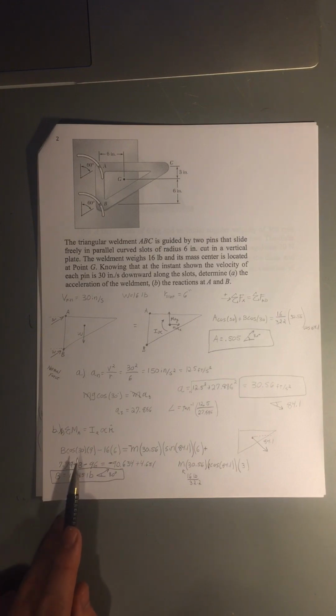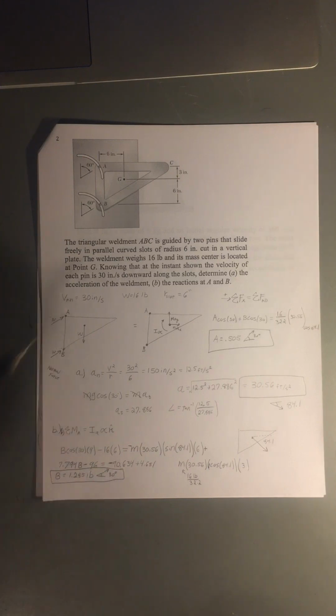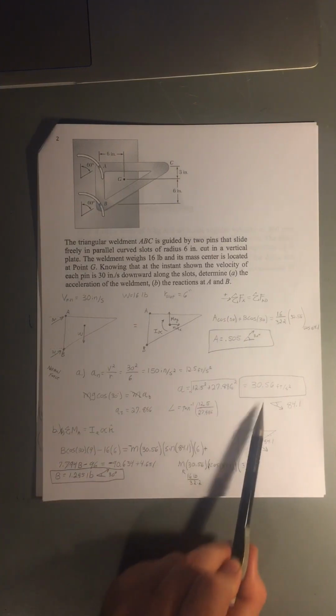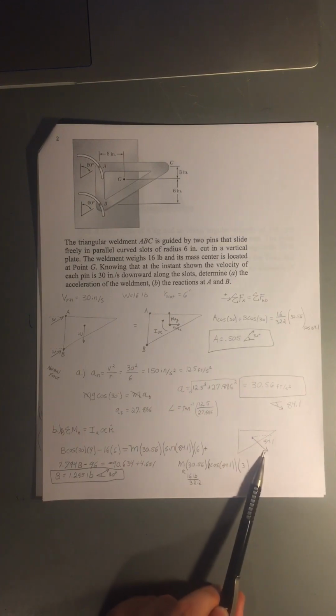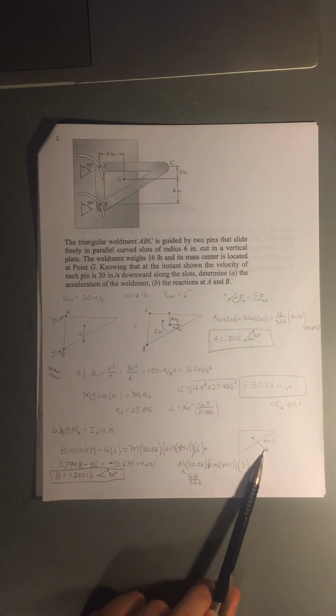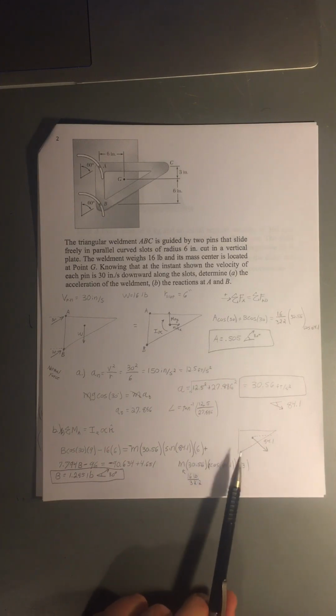We have the force times the perpendicular distance, and then this one here is for point G. So we have the 6 inches times the weight at G. And then we set that equal to the moment in our kinetic diagram here, which is our acceleration. I drew another diagram here to help me visualize that. We have our acceleration that we calculated up above, pointing in this direction, with our angle of 84.1 degrees. And so we need to find the moments for that about point A.